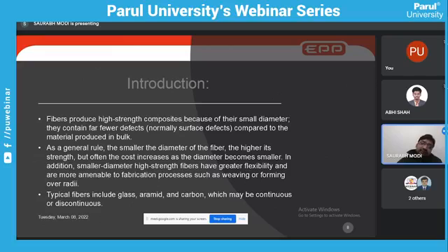Now, whether it's wire drawing or a fiber, the production process remains the same, like you may have studied extrusion. In the extrusion or wire drawing process, we have a big collet and we use a piston cylinder kind of arrangement with a die at the end in which we have a hole, and our diameter will solely depend on that hole. Suppose we have a big diameter hole and a small diameter hole, and you imagine that you are pressing the metal from the back and it has to pass through that hole.